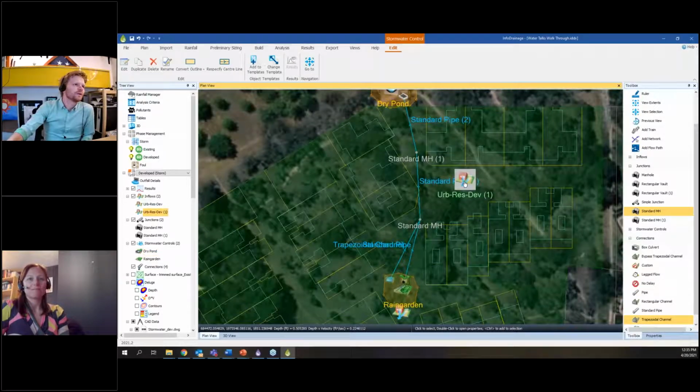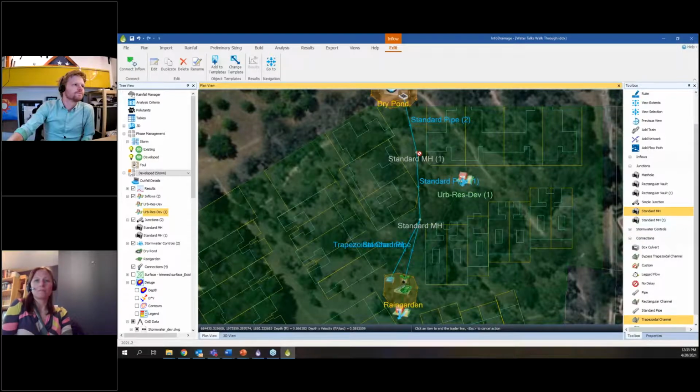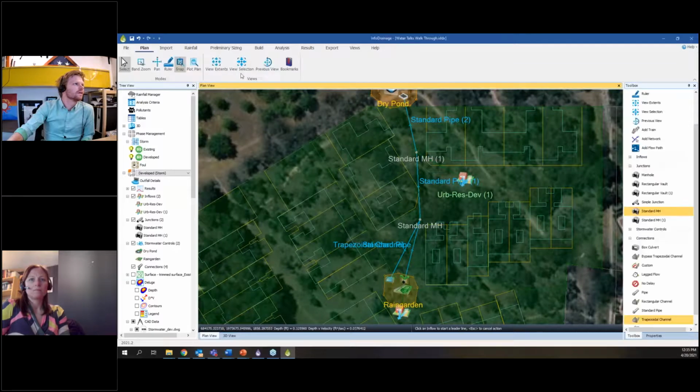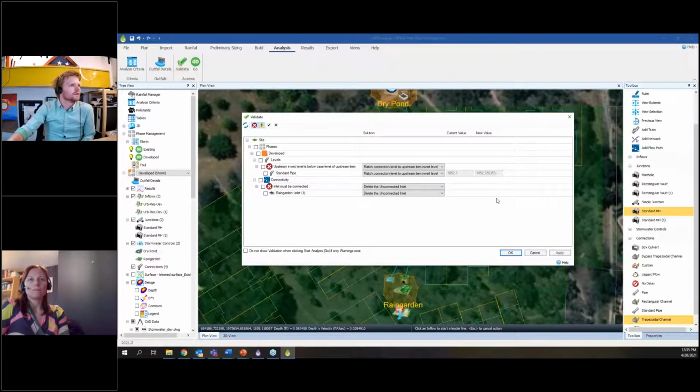So at this point, I'm actually going to reroute this catchment to this manhole down here, since that's more appropriate. And then we're ready to go at this point. I'm going to validate things and see if everything is okay. So it doesn't look like it. I've got a pipe that doesn't quite match up. That was because I tweaked those numbers a little bit, and since the rounding, I didn't see these significant digits. It's not a big deal, so I'm going to keep with that.